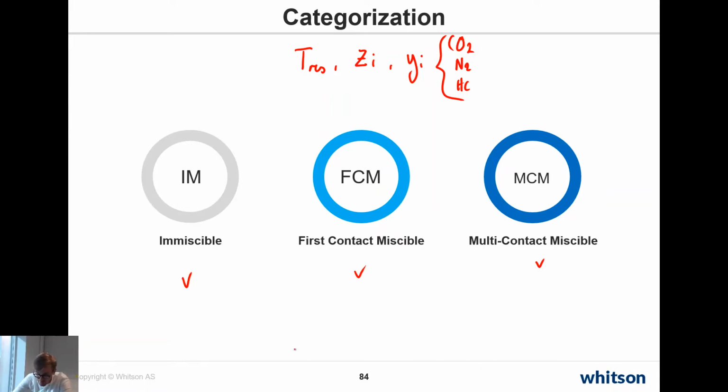mixture. So back to Bob's question a little bit earlier with regards to the swelling curves right here, where we had saturation pressures versus this vapor mole fraction, which you can just think about as GOR, where the axis is from 0 to 1. At this end right here, we only have the injection gas, and here we only have a reservoir fluid.